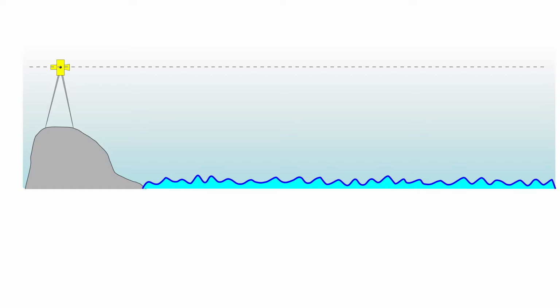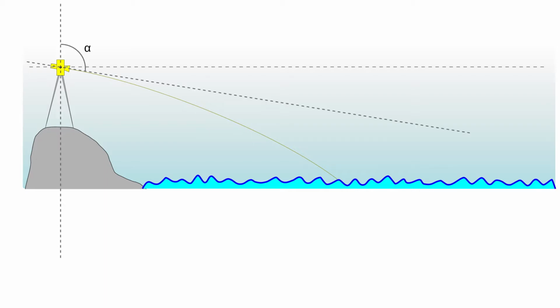Under these standard conditions, light rays in the atmosphere curve slightly downwards, in accordance with the laws of optics. The rays curve towards the denser medium, and the atmosphere is denser at lower altitudes and less dense at higher altitudes, at least usually. This should cause the measured vertical distances to be slightly lower than those implied by geometry alone. I'll show concrete values later, calculated with my own refraction calculator.